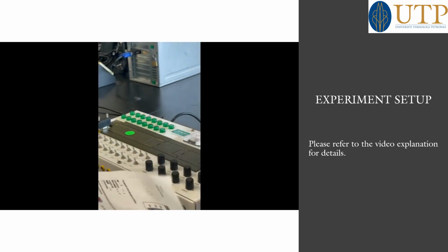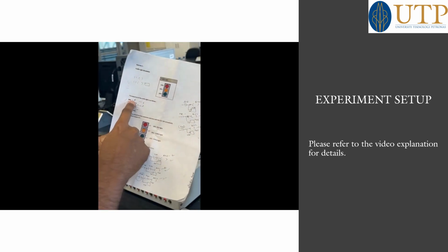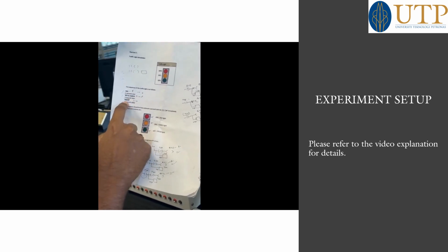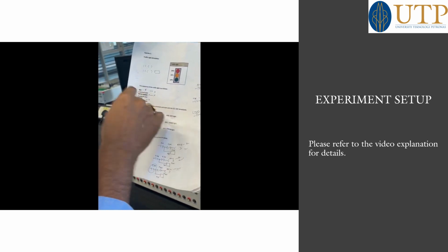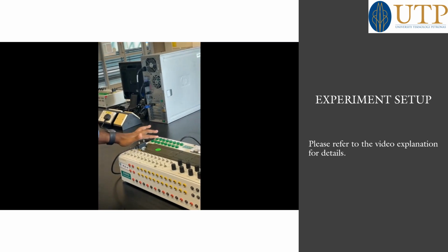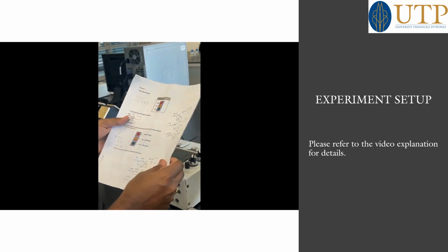So for the traffic light signal, it says that initially on switching on, it should turn on the red light, then after 5 seconds red and amber, then after 5 seconds green should be turned on. Okay, so here the question is that once you turn on I0.0, immediately the red should turn on. After 5 seconds red and amber should turn on. After 5 seconds red and amber should disconnect, and it should turn on the green. After 5 seconds everything should be turned off. So that is the scenario. For that you need to write your own program code here. That's it.